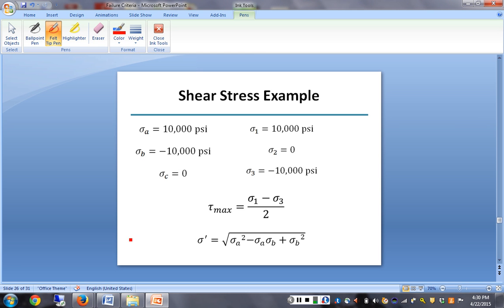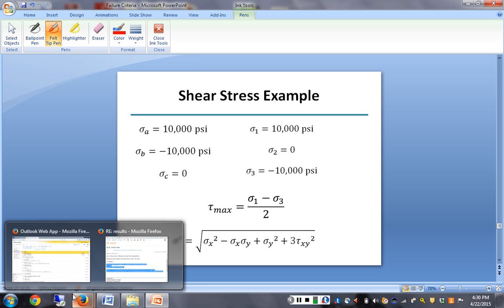I need this to do the Tresca criteria, and I need this guy to do the von Mises criteria. I can do this either using sigma A's and B's or using sigma x, y, and tau. You will get to the same number. It's like going to Walmart down 10th Street or going around 264. You'll still get to Walmart.